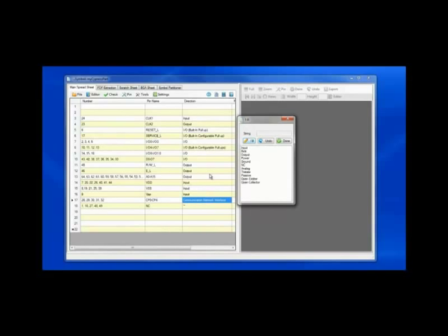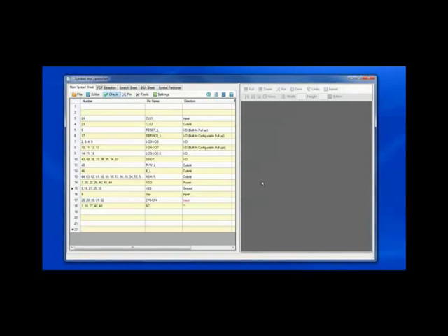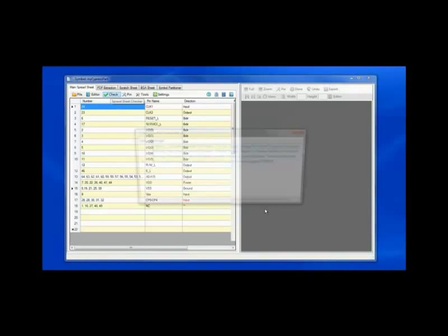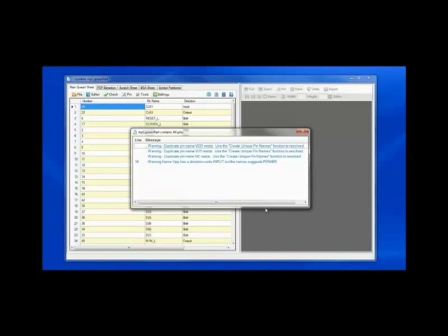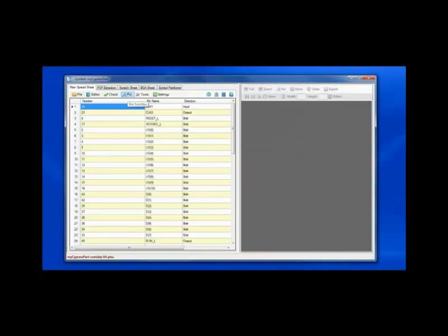And using the intelligent editor that understands the content in each individual column, all I do is click on the column and it'll provide me the available options. I've now tagged the VDD and VSS, checking the data sheet. For some EDA tools, they require unique pin names. We can automate those using the automation function.